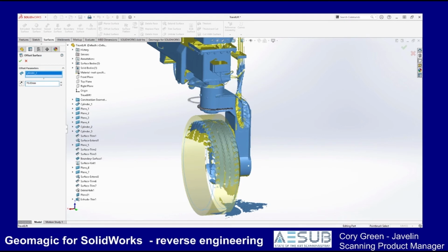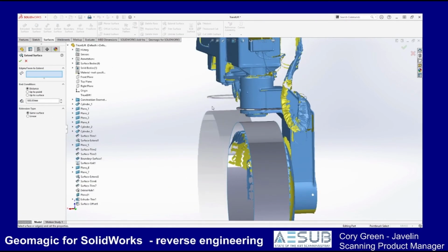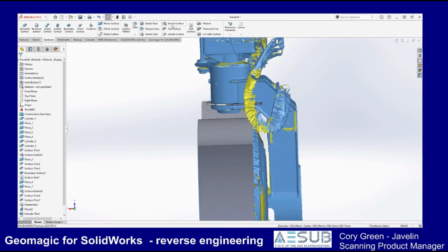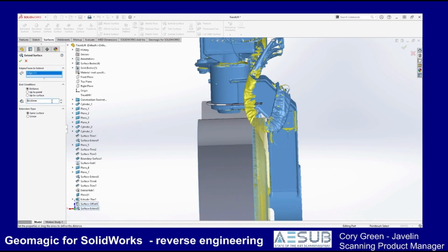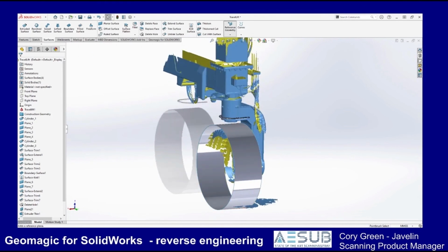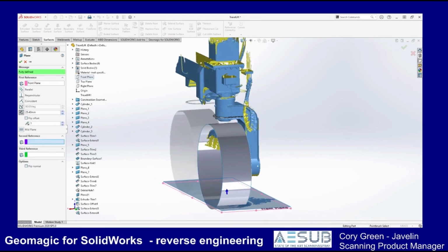Let's keep designing our fender. We'll offset the cylinder we had extracted around the tire, and then we'll extend that cylinder inwards and outwards a little bit so that it covers the full extent of the tire. Next, we'll create a normal SOLIDWORKS plane roughly parallel to the ground based on our existing axis system.